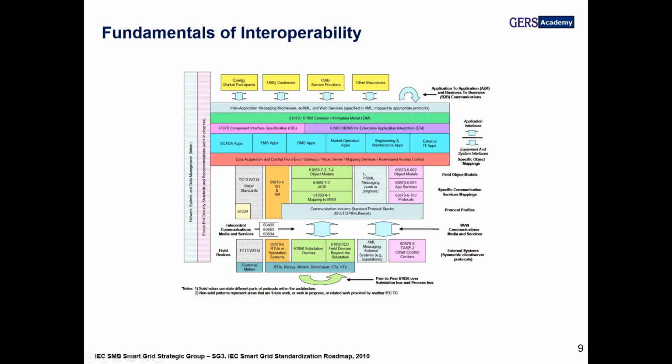However, if we increase the level, we can see here how at a high level we can implement another type of application where the time step between the information is coming maybe not in real time in microseconds. Maybe here we are getting information in step times, but maybe that is coming from the power information. Maybe we are getting information regarding the RMS measurements, and they are being sent in reports. And we are getting here the IEC 61850, but through another message like the MMS protocol.